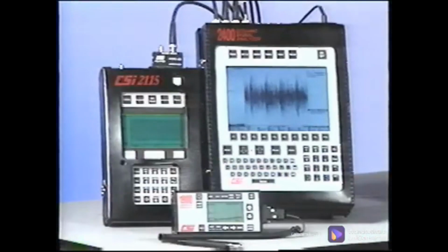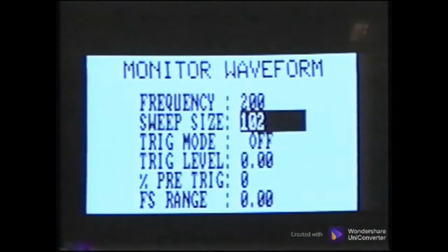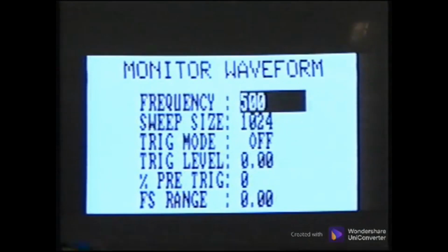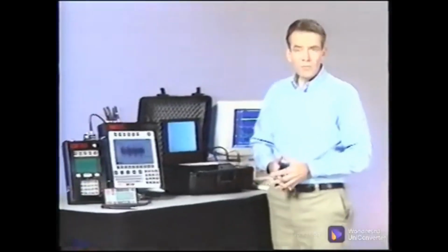View the waveform and acceleration to assist you in the analysis. Remember that decreasing the maximum frequency and increasing the sample size increases the time waveform length, allowing very low frequency events to be captured. However, increasing the maximum frequency and decreasing the sample size provide more detail for high-frequency events. We are confident that by applying the principles in this program, your vibration analysis skills will be enhanced.